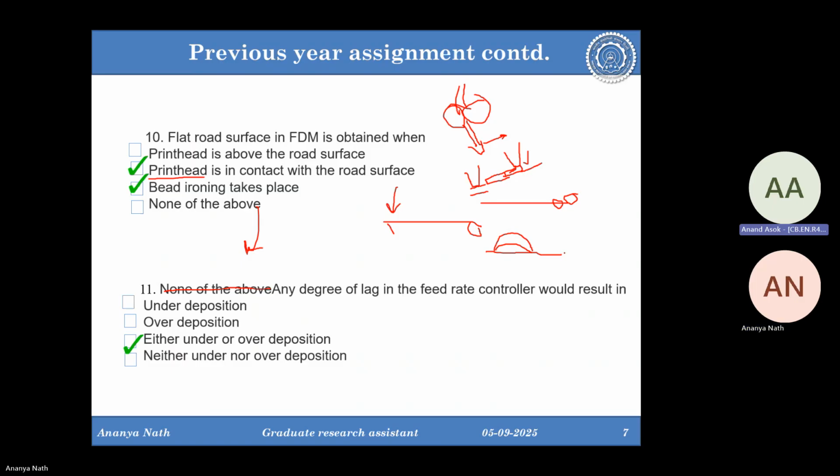Because of the slow rotation of the roller, right? Yes, because of the slow rotation or your feeding is not proper, there is slip, or your tension is not maintained. Mainly it's because of the roller movement. Your rotation is not proper in the roller. If the velocity is not high, it's slow, and your feeding is not proper, then you can get over deposition as well.